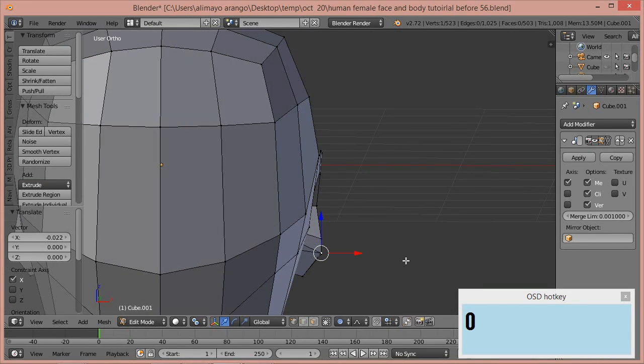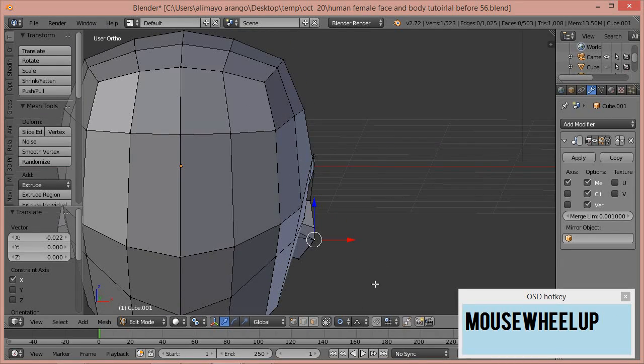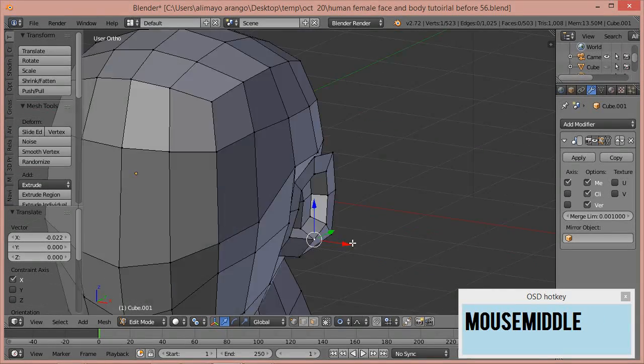I'm going to hit O to turn on the proportional edit tool. I'm actually going to hit Alt O, which turns on a special kind of proportional edit tool. You see how this is like a donut kind of here? Alt O is basically connected proportional edit. So I have this dot selected here. Even though I'm close to here, it should only deal with the vertices that are connected to this vertex and not affect the vertices there.